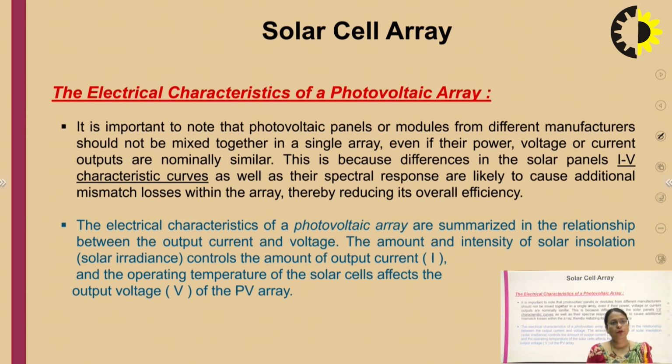Now, the characteristics of the photovoltaic array. It is important that photovoltaic panels or modules from different manufacturers should not be mixed together in a single array, even if their power, voltage or current ratings are the same. This is because differences in the solar panels' IV characteristics, as well as their spectral responses, are likely to produce mismatch losses within the array, which will definitely reduce the efficiency of the overall panel, right?